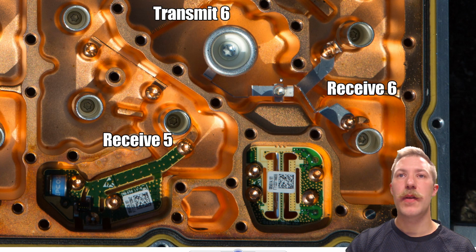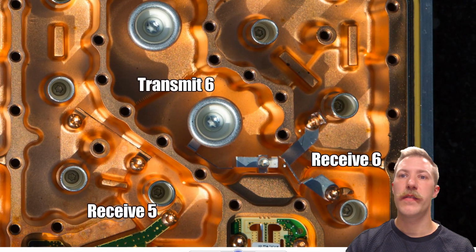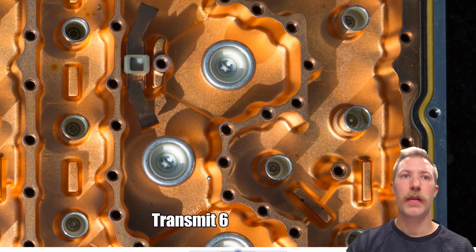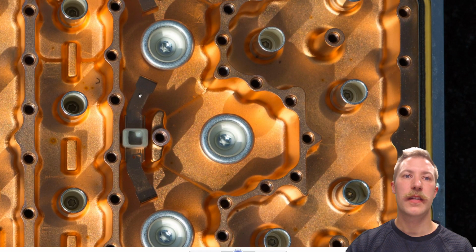Now if we look at the transmit and receive part channel over here at the receive and transmit 6, we can see that the transmit part usually has larger resonators due to the higher transmitting power compared to the receiving power. But we can also easily recognize a transmit duplex filter by the amount of couplings that we see here, which is an isolated piece of conductive material that sits between two cavity chambers.